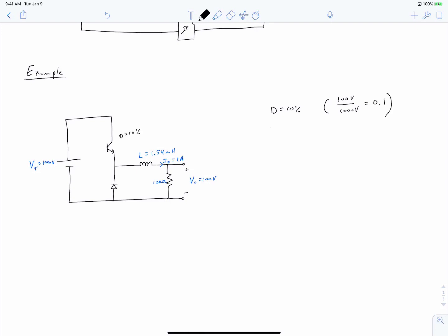And in this problem, we're going to assume that V peak, which is the peak value of our triangular waveform PWM carrier, is equal to 10 volts. And this means that we must have a gain for it of 1 over V peak, which is equal to 1/10, which is equal to 0.1, which is in fact equal to negative 20 decibels.